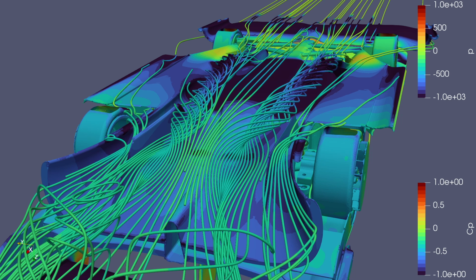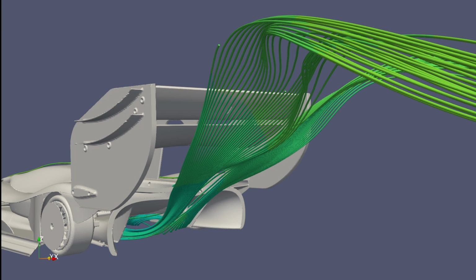Okay, so the last interesting bit about the floor, as you can see from the pressure maps, is that there is downforce being generated across almost the entire floor. And this is really ideal, and it's not always achievable because of those pesky rules. But the reason we have downforce over the entire floor is a combination of the giant rear wing and inlet vortex generators.